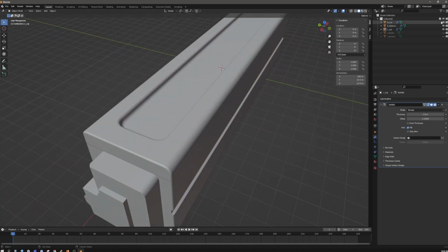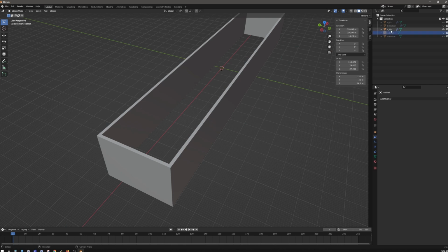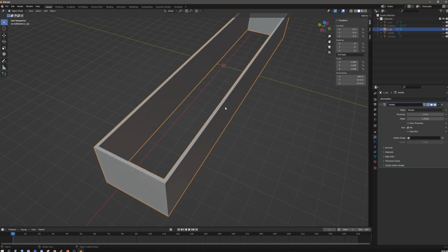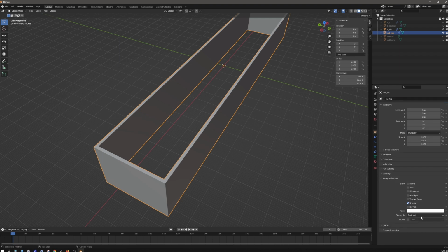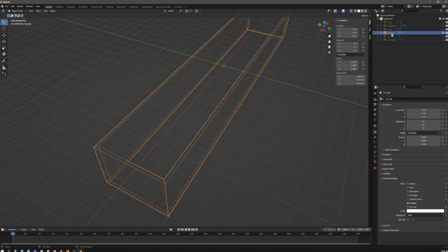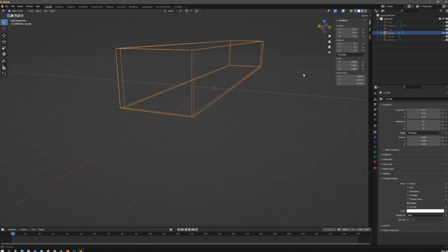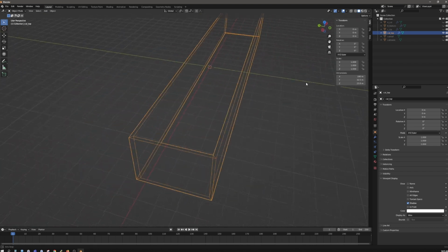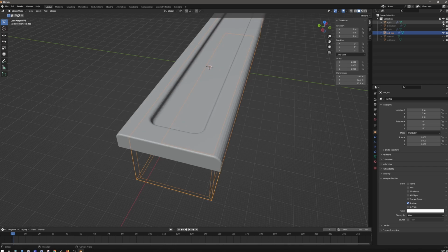So let's go ahead and turn everything off except for our lip. And because it already has the thickness that we want, let's go ahead and, again, Shift D, click so it doesn't go anywhere. And then we'll be using this as a cut. So we'll go cut top. All right. For now, we're going to leave the lip off. And then we're going to turn on our lid.